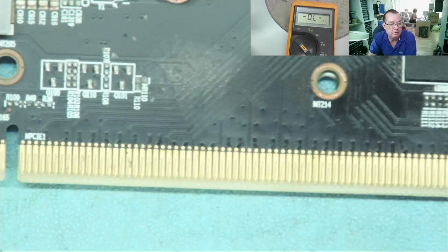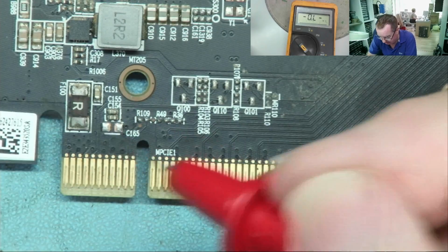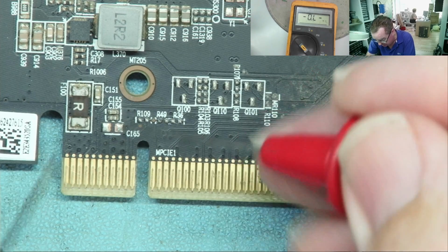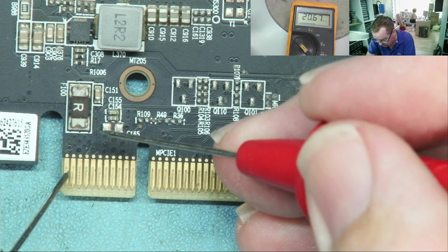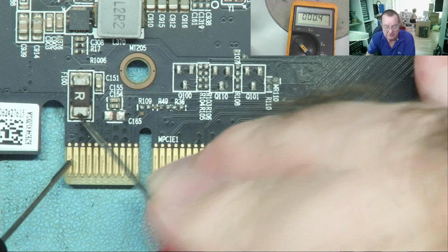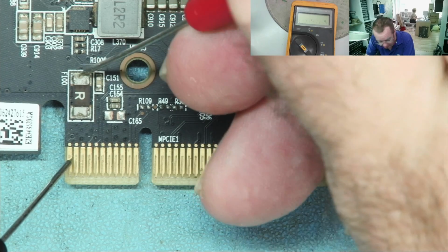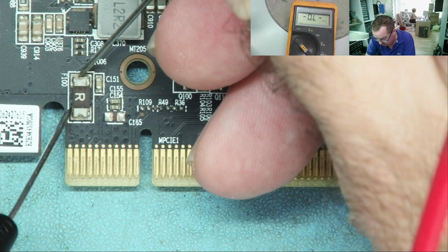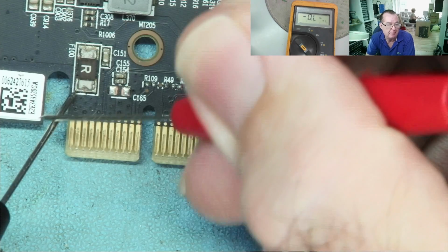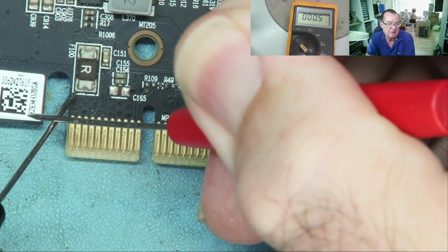Let's have a look. Well, in fact, this is a fuse marked F100, so that should be checked as well. Probably comes from the 12, you would assume. Yeah, reading 0 ohms. The fuse should read 0 or close to it, yeah. I mean, my meter doesn't zero properly. If I go short, you see it reads the same 0.4, okay?